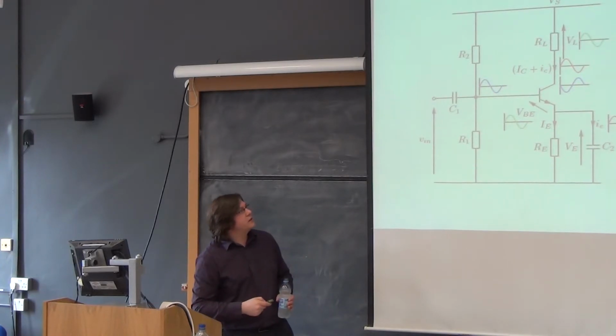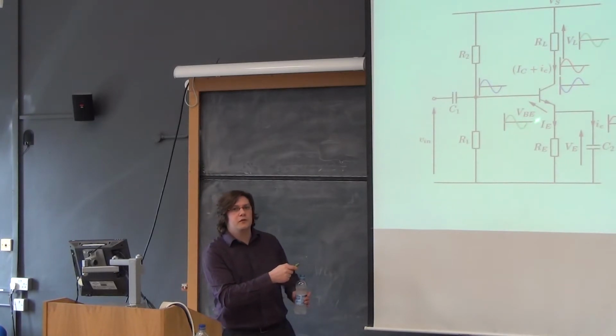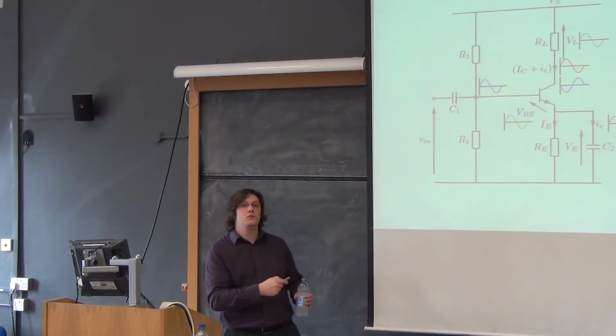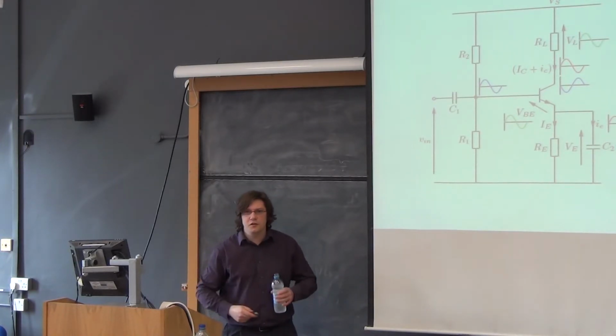And if the transistor gets a bit hotter, a bigger current will flow, and a bigger voltage will be dropped across VE. But this point is fixed. So all that can happen is VE has to get a bit smaller, which turns off the transistor a bit, which causes less current to flow, which means it cools down somewhat. And all this is happening all the time, and we're stabilising the operating point.